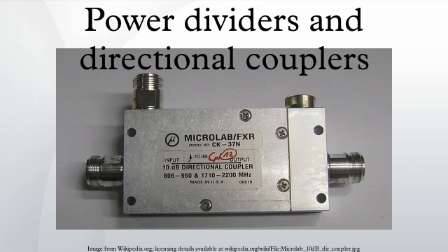Although a negative quantity, the minus sign is frequently dropped in running text and diagrams, and a few authors go so far as to define it as a positive quantity. Coupling is not constant, but varies with frequency. While different designs may reduce the variance, a perfectly flat coupler theoretically cannot be built. Directional couplers are specified in terms of the coupling accuracy at the frequency band center.